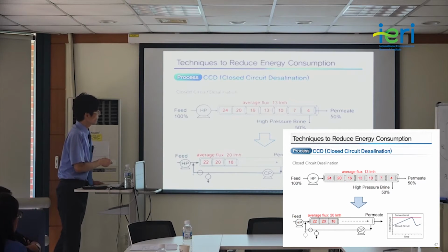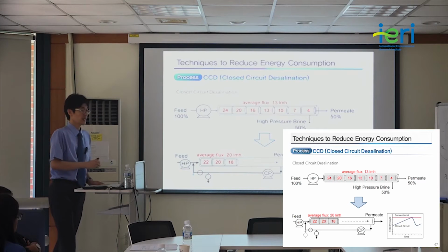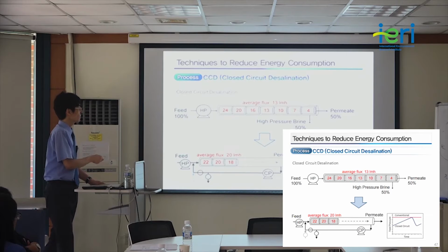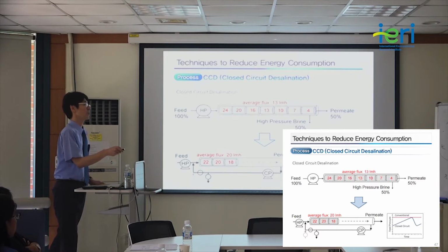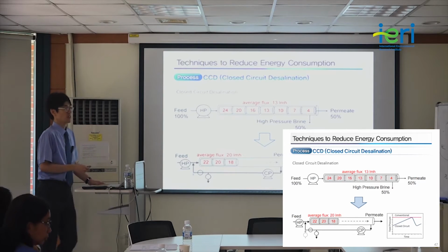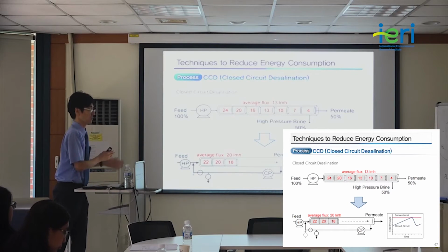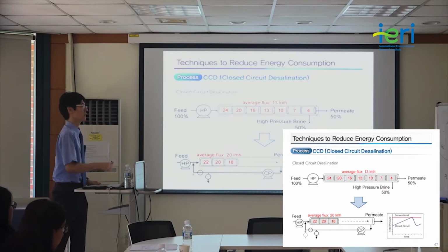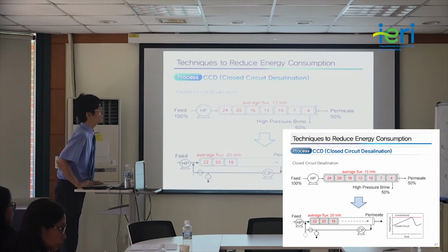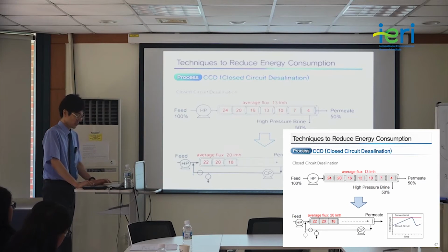The nice thing is, during this operation, we can increase the applied pressure in a stepwise manner. So the pressure follows the osmotic pressure requirement in the system. So we can simulate this kind of situation. So we can minimize the difference between the ideal theoretical pressure requirement and applied pressure requirement. So we can take out this part so that we can again reduce the specific energy consumption.